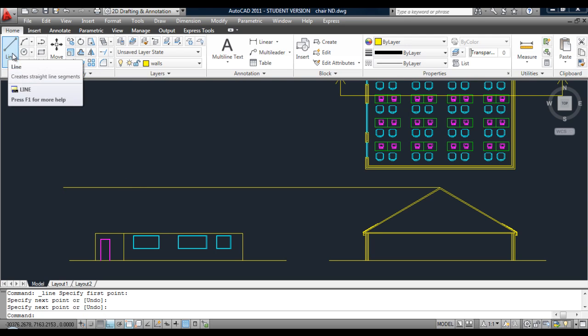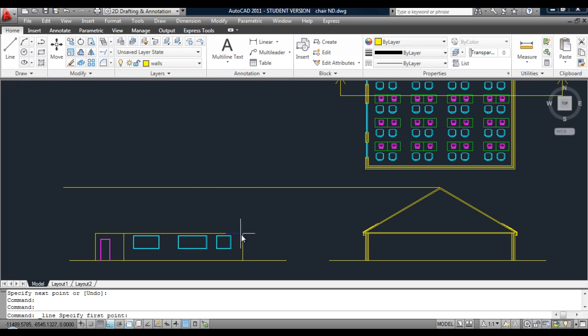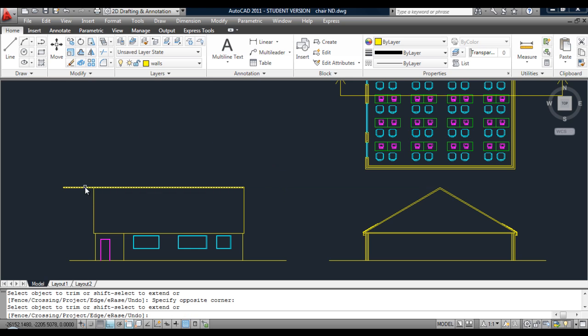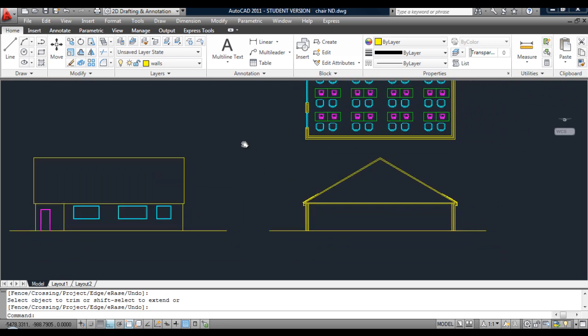Then you can finish off your elevation. So draw a line, say from this point out to the side, 150 millimeters overhang to perpendicular, to the same as the opposite side, from here 150, perpendicular, and finish off your side elevation with a trim, like so. So you'll then have an elevation and a section. Next we'll look at the foundation detail.